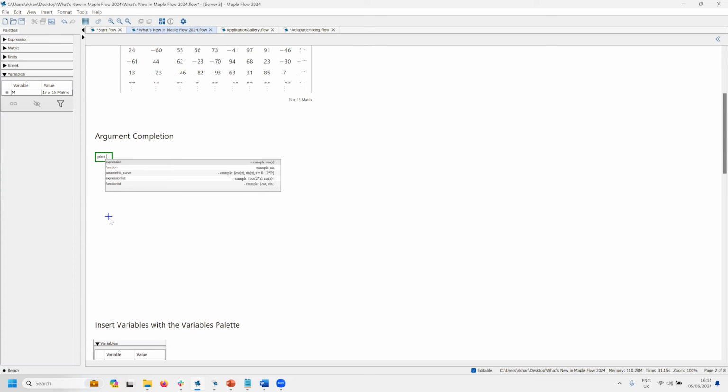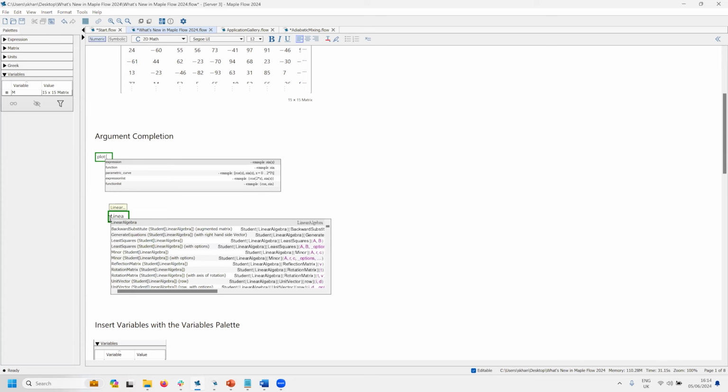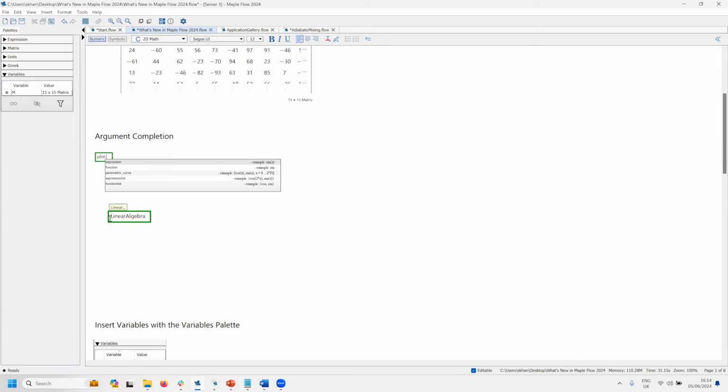Well, if I type in the first few letters of a command, and I hit the command completion menu keystroke on my keyboard, which is Control Space or Escape, the command completion menu pops up on screen. These are the commands that would naturally be completed by what I've typed in. I just want to pick the first option. So I hit Tab.